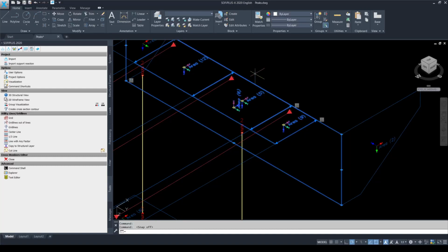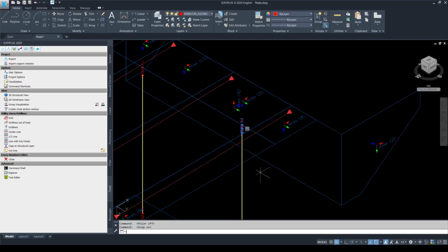The other problematic area could be the edge between the vertical wall and the bridge deck, since from the vertical and horizontal deflection or displacement of the bridge deck, extremely high internal forces can occur in the vertical wall that make the design of the vertical wall impossible again.